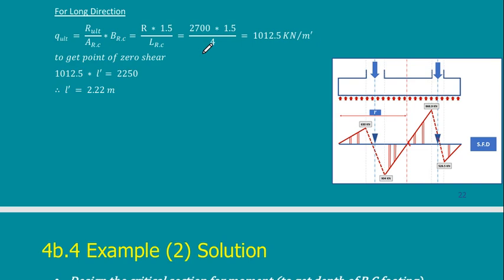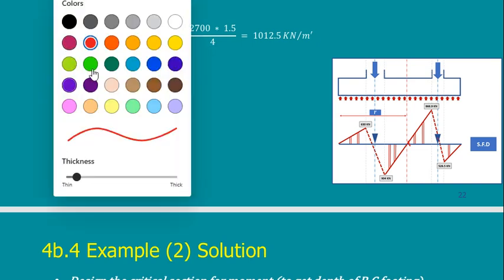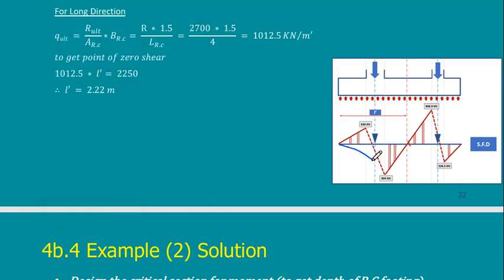What will be the shape of the bending moment? I will have a bending moment something like this. This is the moment of the cantilever. This is the other moment of the cantilever. Of course, here the moment is less than there because here the distance is less. And I now have another bending moment here like this, and this is the point of the maximum moment.